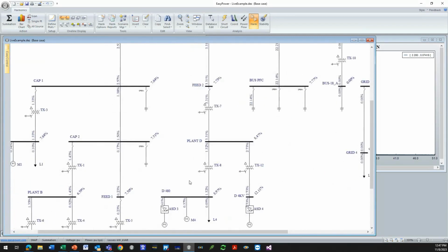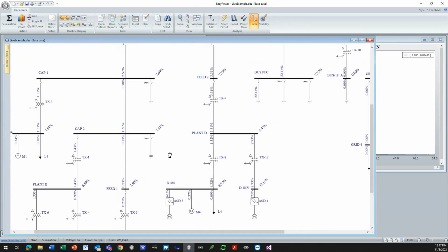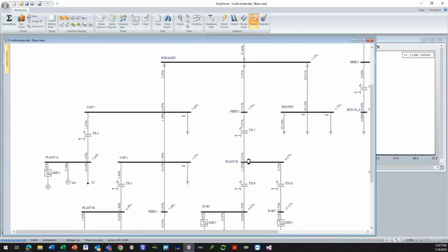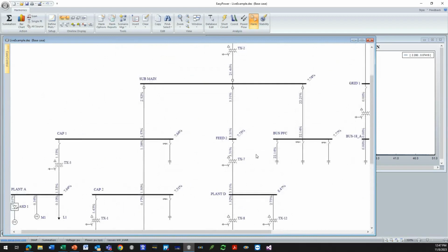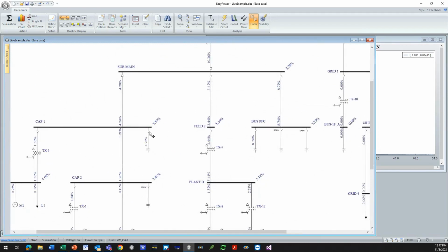And of course, if we wanted, we could take these individually offline and see how the distortion changes based on individual harmonic loads being present on the system. So in this case, we're getting a rather high distortion. We're up well over 5%. And there's other combinations. Oh, but look at this one, it drops to 3.7. This one drops it to 2, but if I take this offline, oh, look at this, I'm all the way up to 9.6% distortion down here at this location.